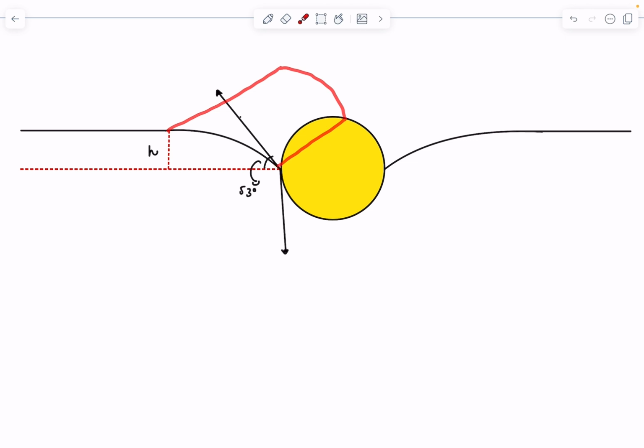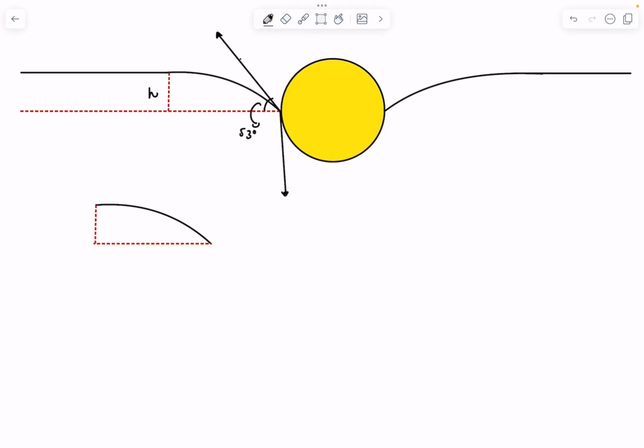So what we're going to do is chop this particular part of the fluid surface, which means the part on the right will be pulled towards the left by surface tension forces. Let's draw its FBD over here. If we look at this fluid layer from an angle, it will look something like this. So we sliced this fluid layer along this plane, so the fluid on the left would pull on this layer towards the left. We have to mark surface tension forces like this. This is the force that the fluid layer on the left will exert on this line.